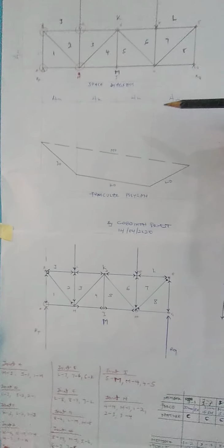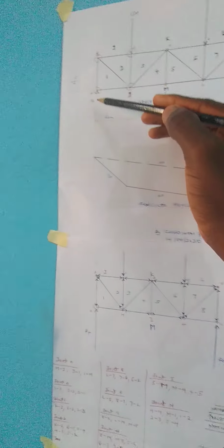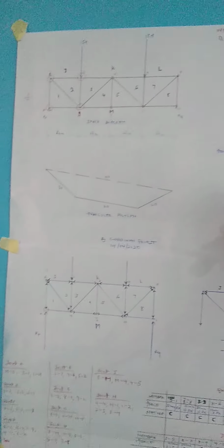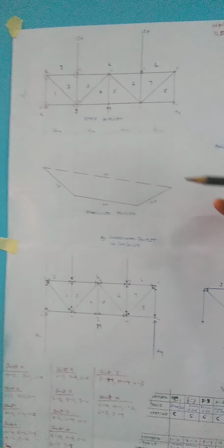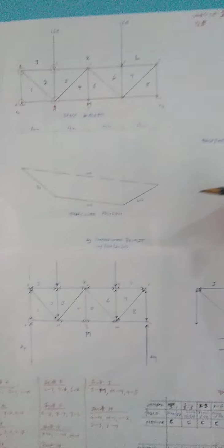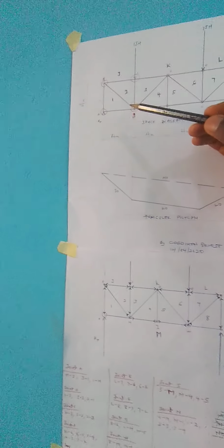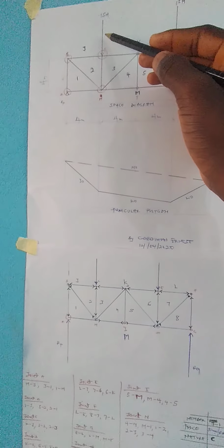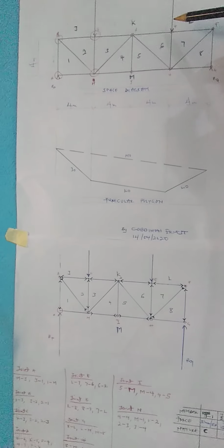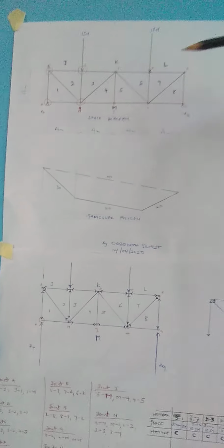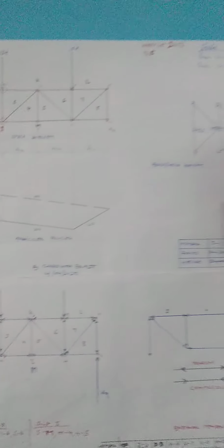The first question was to determine our reactions RP and RQ. And this determination was to be done graphically using drawing procedures throughout. It can also be done analytically, that is by mathematical method. But using the drawing method, we have to first and foremost convert these forces, or this load up here, which is 15 newtons, in our polar diagram.